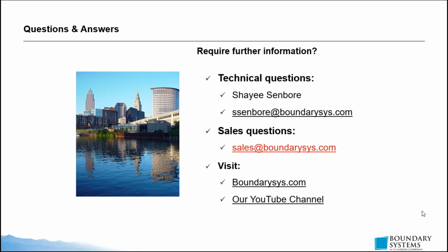Another question in here: do you have the ability to change units and mix different units? The answer for that right now is no. Right now, Creo Flow Analysis only works with essentially the SI unit system. There's an update coming for future releases, somewhere in the Creo 7 or 8 timeframe, where they will add the ability to convert units, but right now the answer is no.